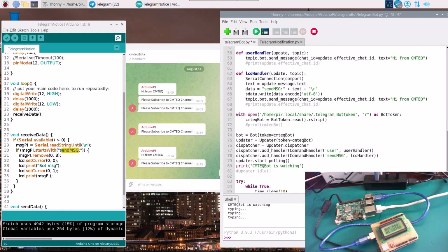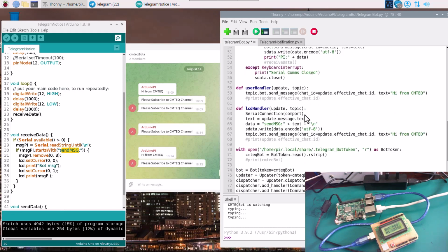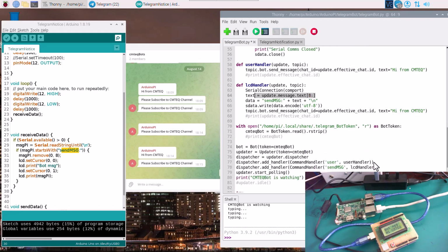So we're going to remove how many characters will that be? It's going to be 1 2 3 4 5 6 7 8 and a slash. So we need to remove all of that. To do that, we're going to pass the bracket here, 8 and a colon, like that. That is basically going to remove the first characters and then pass the rest to the serial port. Let's go ahead and try to run this and see if we're going to get any success here.